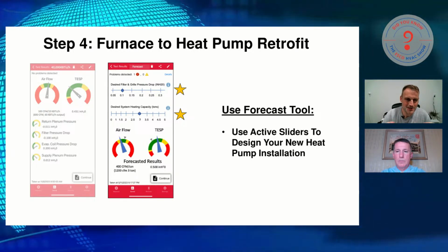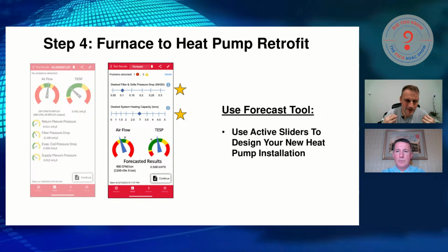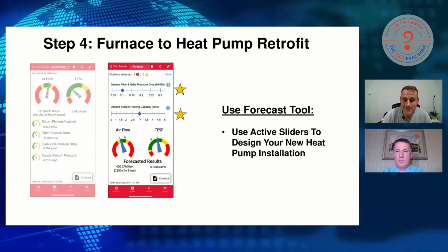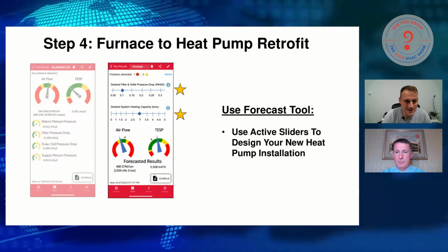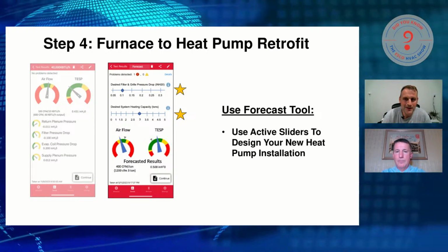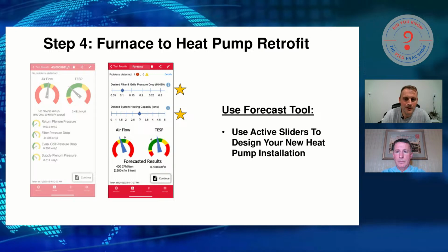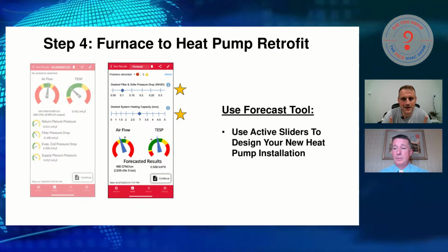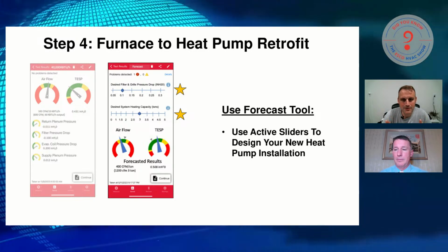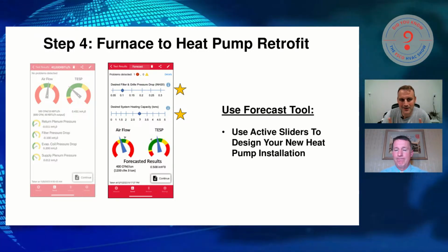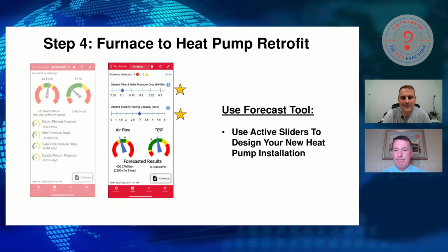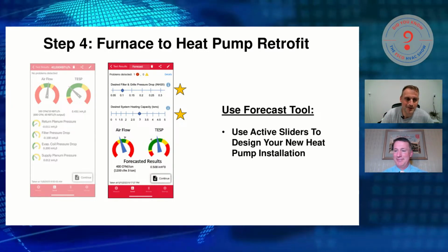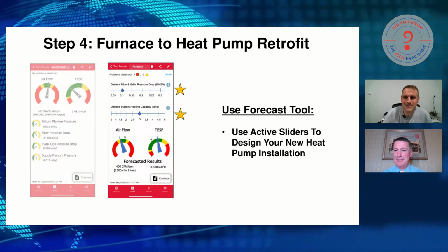When you move those slider dials, you're essentially changing the components of the ductwork that are expected sometimes to be changed during a change out, retrofit, whatever you want to call it. When you move those, all the homework is being done for you on the dials below. So your airflow and your total external static pressure, those needles are going to move. That's why they're blue. Those are my active dials, and they're going to rotate. And that's how you're basically designing your retrofit to see if what you want to put back is capable or not.